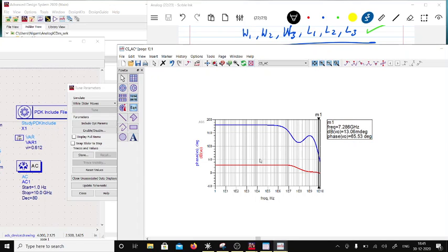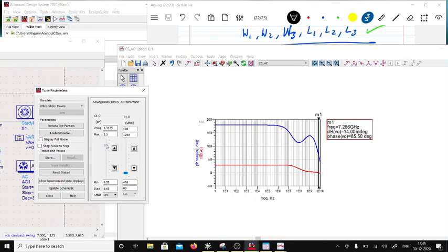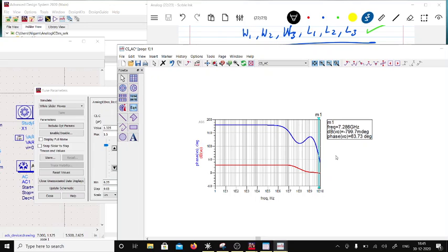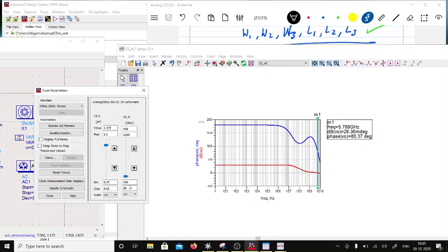Okay, so you see here there is the gain of 0, and I now have 65-degree margin. Okay, let's pull this point to the left. So there are different things in this. When you do that, you can cancel the second pole, you can do lots of things here. So 28, 28. So now I have 80-degree margin.